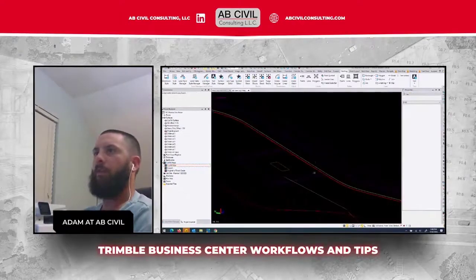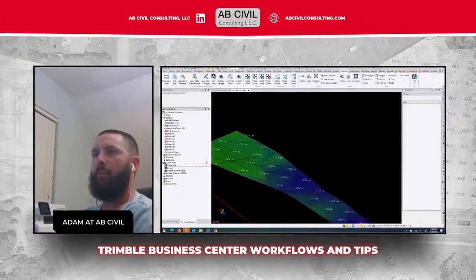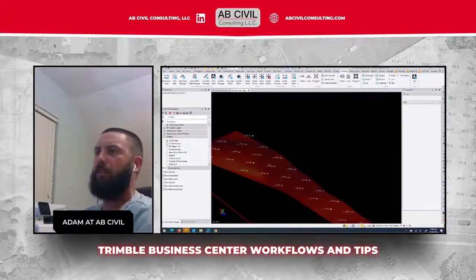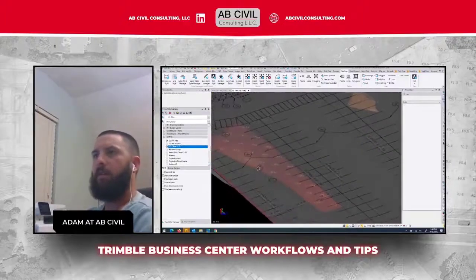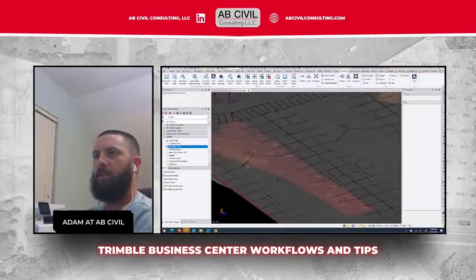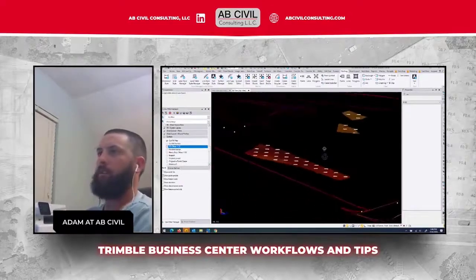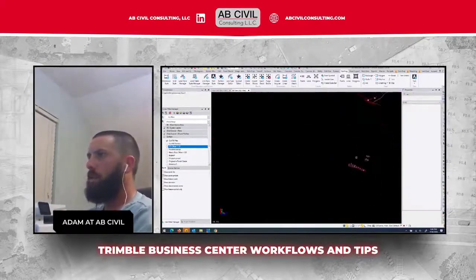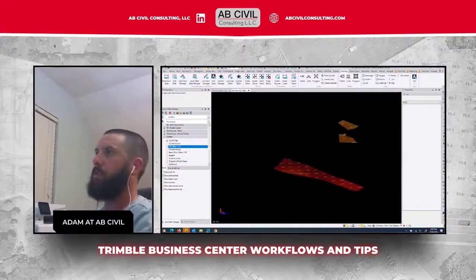So if I were to go into 3D view, that cut fill map was draped right on top. Let me see. All right, so I turned the surface off. So now in 3D, there I can turn on my offset surface. It's a little hard to see through it, but now the cut fill map is draped onto the final surface that was used in the cut fill map. If I were to turn that setting off, you will find this surface, but it's down here at the actual elevation of the cut fill map, which in this case is all about -2 elevation.